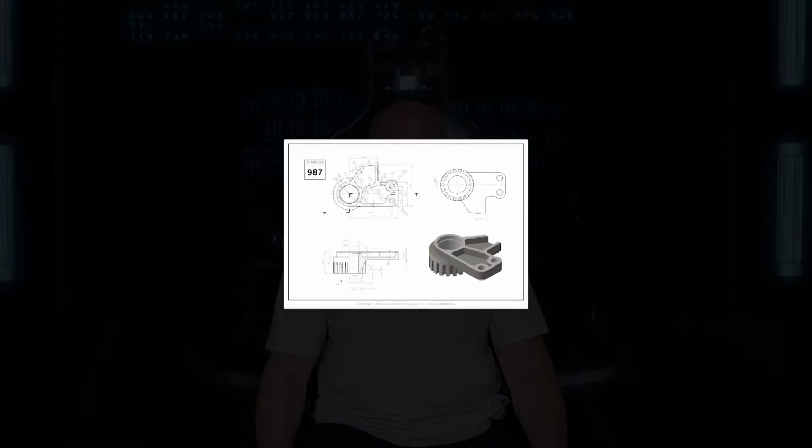In today's lesson we will create a complete mechanical part. You will learn how to use Boolean tools, shell, pocket, pad and circular pattern. More importantly, I will show you the correct order of using these tools to create the model. So stay with me and let's start today's exercise.